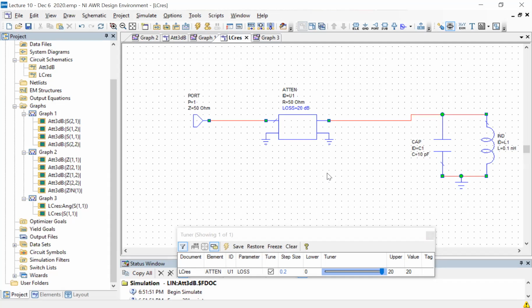The reason for doing it effectively as a 2-port at low temperatures is because you don't want the signal path to be the same for going in and coming out. This is going to be part of the next lecture. It's related to the fact that the incoming line has a lot of attenuation deliberately put in to protect the device from the noise, whereas for the signal coming back, you want to capture as much of it as possible.